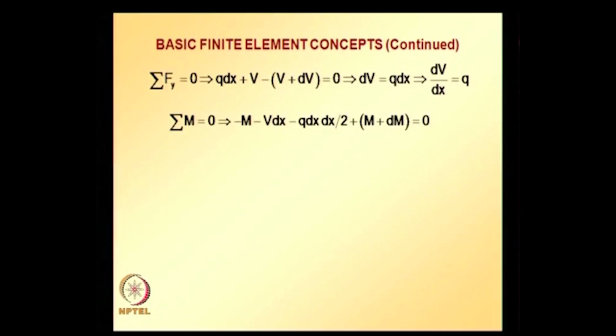The sum of all forces in the y direction equal to 0 gives the spatial derivative of shear force equal to the distributed load applied. The sum of moments equal to 0 gives that equation.